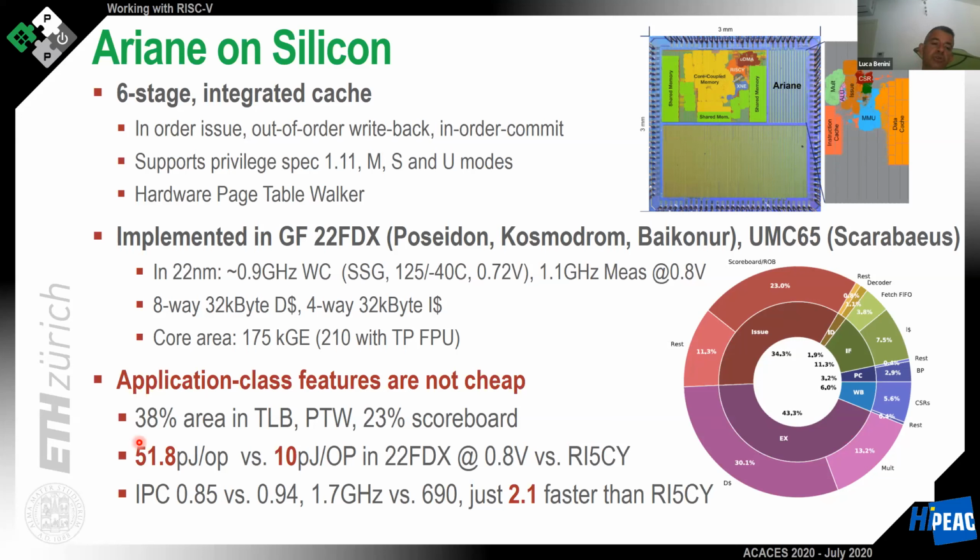So this processor is faster because in this technology, a microcontroller runs at roughly half of the frequency, so 500 megahertz. Here we are running at 1 gigahertz. So speed is double, but the cost in terms of power is much higher, so that we have even a factor of 5 worse energy per operation. So it is not for free.